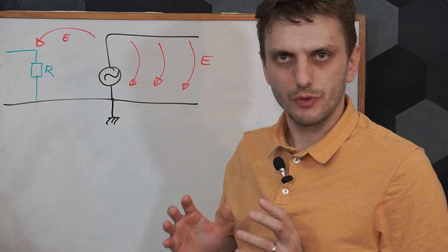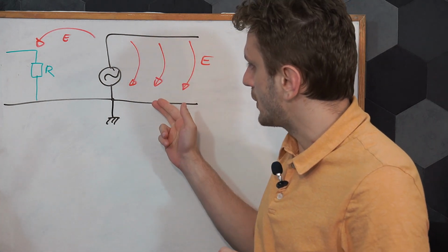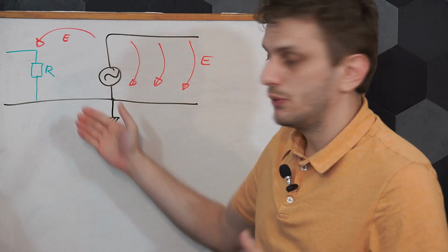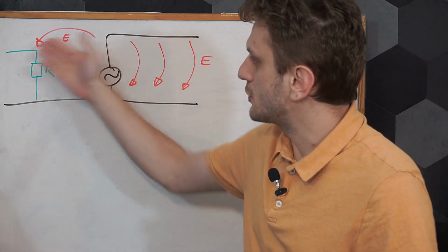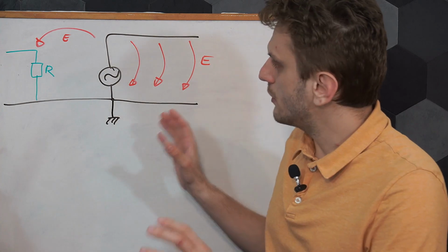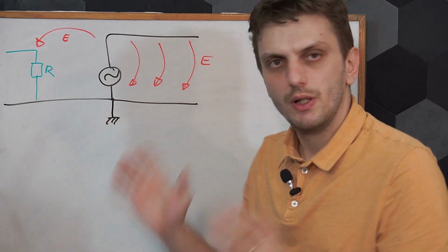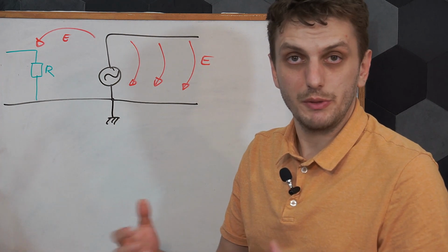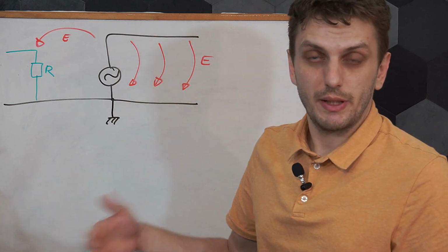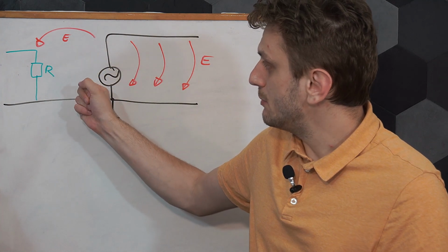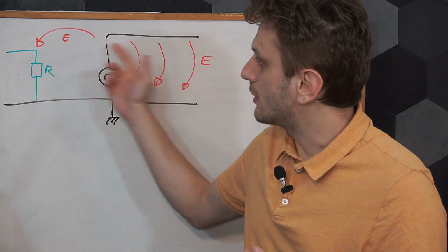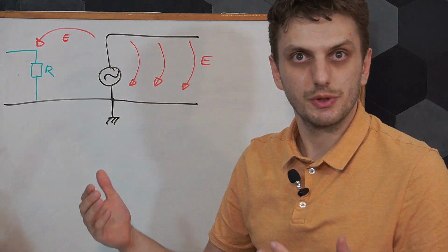Now, it's important to observe though that your electric fields won't just close where you want them to close, but they will go to any nearby conductor with which there's a voltage potential difference. So if there's any sort of sensitive circuitry, some of the fields that hit it might end up causing problems. And we can see just how this system would work with today's experiment, in which I'll be using my spectrum analyzer with its tracking generator. So the noise source will be represented by the tracking generator, and the spectrum analyzer's input will be our sensitive circuit. So this way we can measure just how strong our fields are coupling and creating issues.